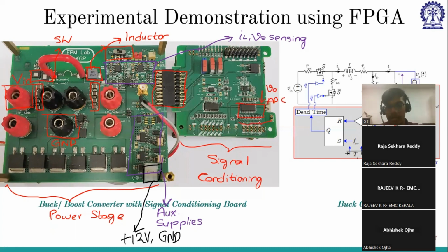So we have used a 10-bit ADC. So the output will be 10-bit in digital format. And now these digital signals will go to the FPGA, which is sitting right below this top board. And then that digital signal will be coming back, because whatever we perform in the actual world, all are analog signals. Only the controller, the FPGA, will perform all the actions in the digital domain. So whatever signal we have to generate back, it should be analog. So that's why for that purpose, we have another DAC. This DAC will be used only in current mode control, not voltage mode control.